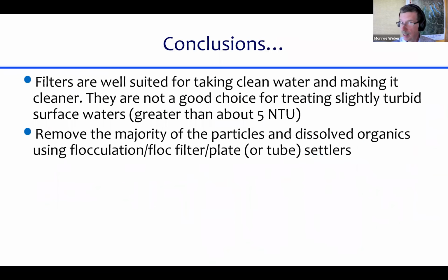Okay. A few conclusions. Filters are really well suited for taking clean water and making it cleaner. They are not a good choice for treating slightly turbid surface waters greater than about 5 NTU. Meaning that if you look at the water and you see that it's dirty, it's too dirty to treat with a filter.